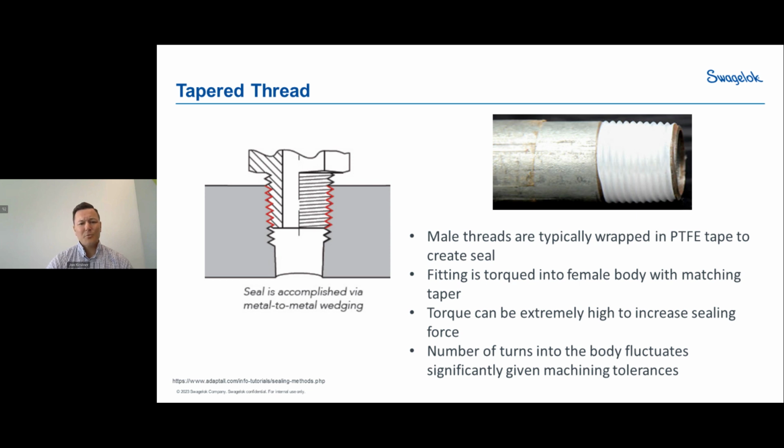The torques can also be extremely high, and probably the most problematic, at least when you think about using these practically in the field, and anybody who has gotten frustrated trying to align a gauge that has an NPT end on it to look nice and neat the direction you'd like it to go, is that NPT or tapered threads generally aren't gaugeable.